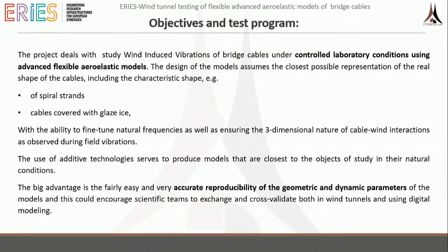This procedure, which I will show, can present any shape, like spiral strands or cables covered with glaze ice, etc. And the important thing is that we can finely tune the frequencies of this specimen, so that we can also simulate naturally three-dimensional behavior of this specimen.